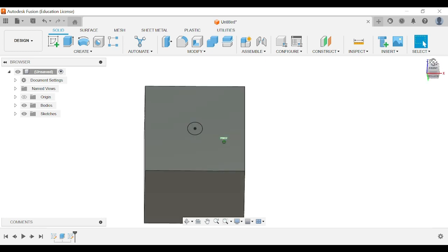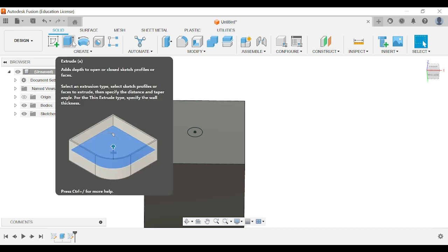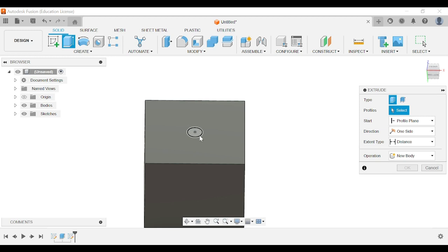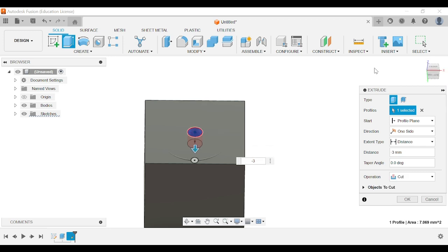Now I can extrude cut it. When I say extrude cut, I mean I'm going to create a hole inside my dice. That's the same tool as before, the extrude tool up here. The extrude tool can extrude things up, and it can also cut things. So if we press on extrude and press on the center of our circle, we can put in negative instead of positive. If we put in a negative, it's going to extrude cut the circle inside the shape.